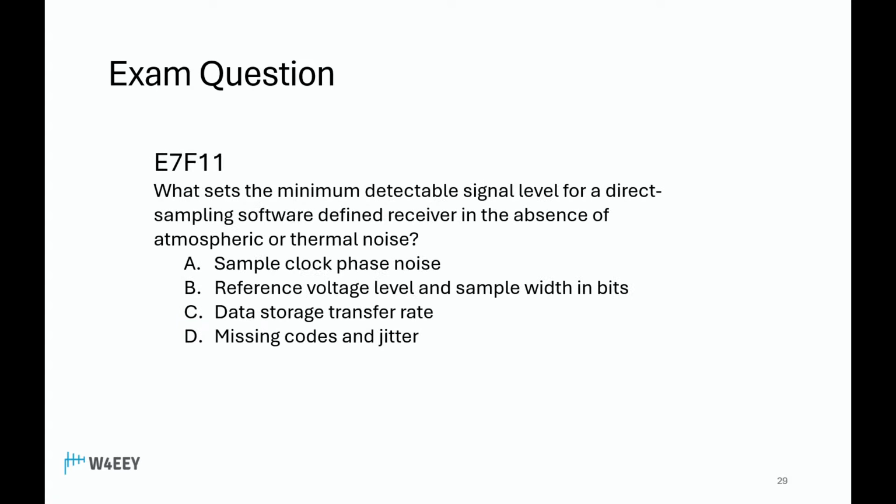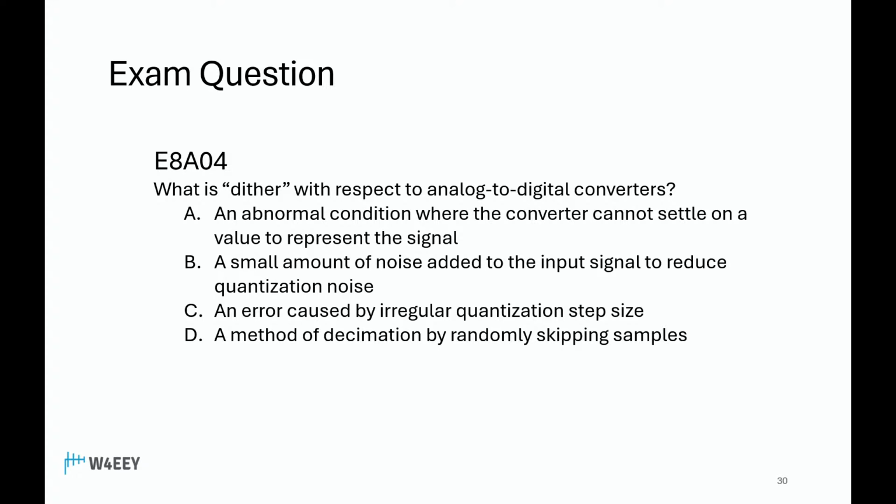What sets the minimum detectable signal level for a direct sampling software-defined receiver in the absence of atmospheric or thermal noise? Bravo. That is bravo. Reference voltage level and sample width in bits. You're doing great. What is dither with respect to analog to digital converters?